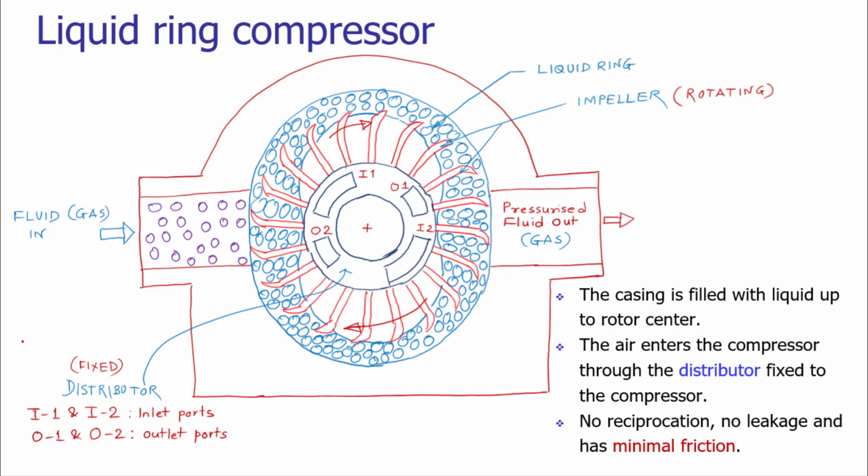Due to the friction, there is wear and tear of the mechanical parts, and due to the wear and tear of the mechanical parts, there will be gaps. So those gaps are creating leakages of the compressed air inside the mechanical system. These leakages are affecting the efficiency. So we need to have a leakage free system, or a system which is providing minimal leakage during the operation.